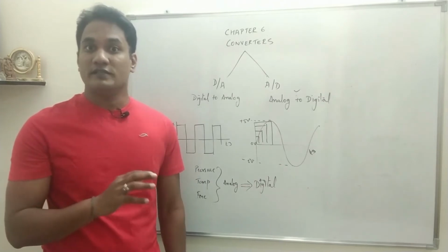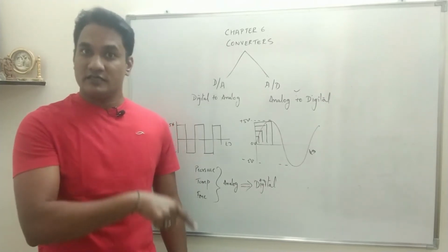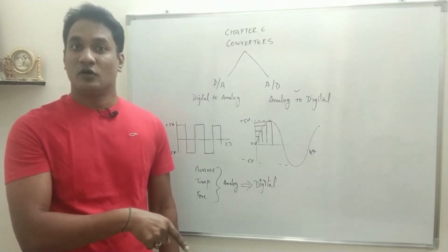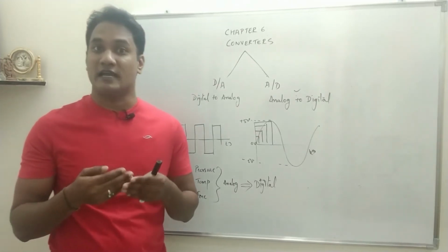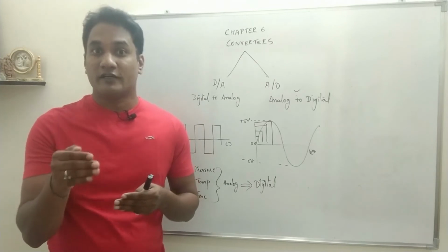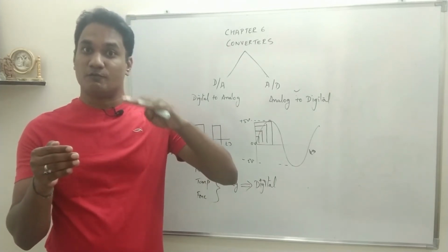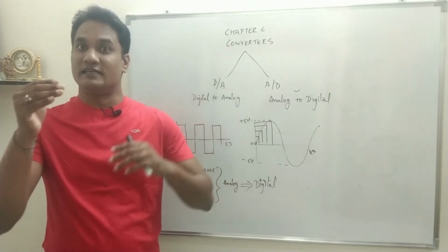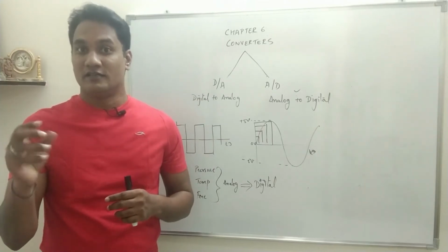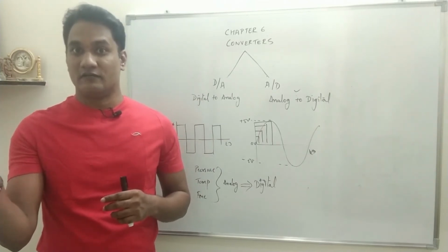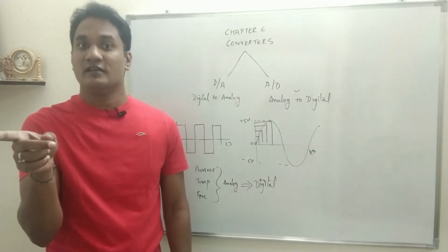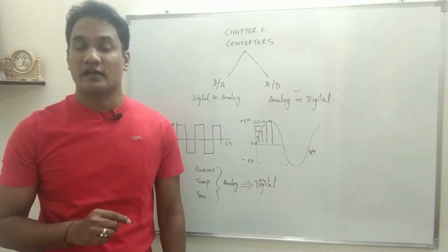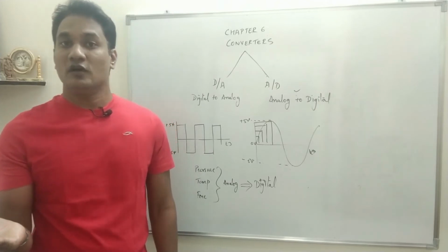So what you have to do is, if the temperature goes beyond the range, the burner should be switched off. But who will do that? Of course, the computer. The computer will understand the logic, and if the temperature goes beyond a certain range, the digital signal will generate a signal which will turn off the burner. So when the digital signal has to generate a signal to turn off the burner, it will be converted back into analog.